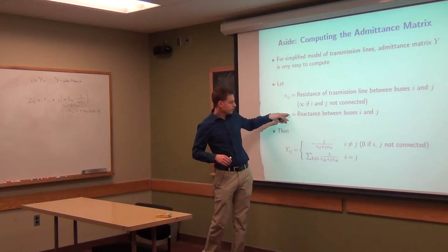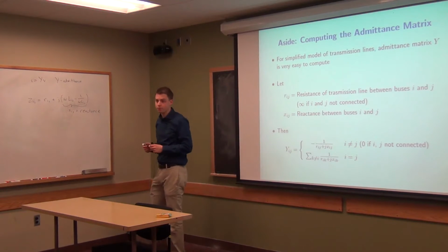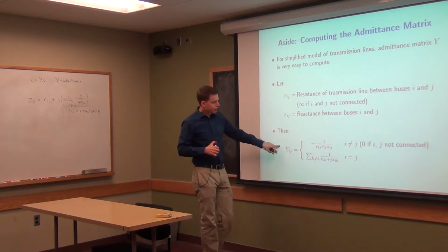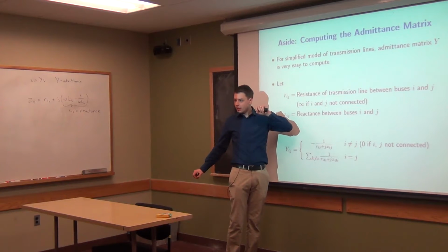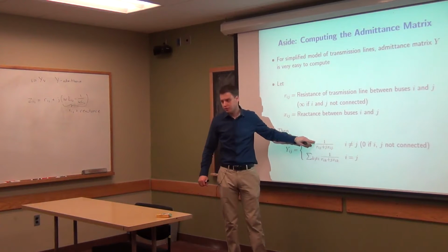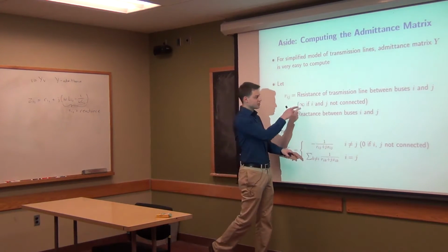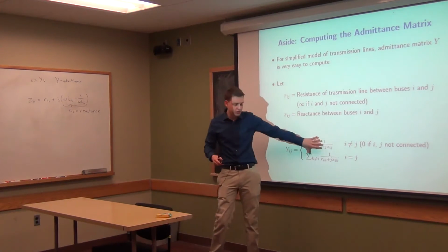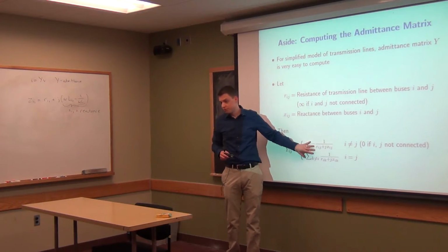So given these two things, our admittance matrix actually has a very nice form. All it is is the following. It's a symmetric matrix where the ith element for non-diagonal elements is just 1 over the impedance. And I could just write this as the total impedance here. I'm separating it out into these two things, so it'll be nice to think of it later on as some of these things being 0, some of them being positive numbers. But this is a definition.